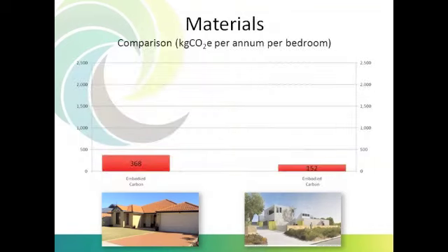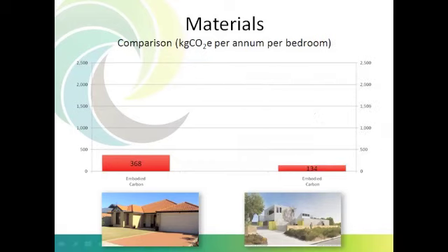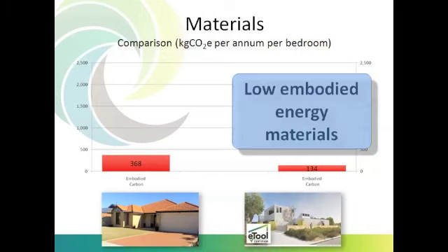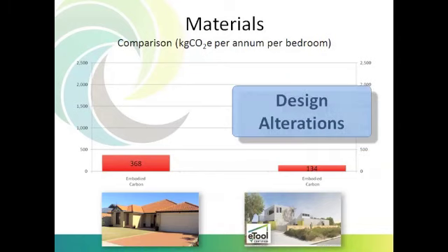Now let's look closely at the makeup of these buildings. Materials are selected for the design process. The new design with shared walls, high lifespan and light frame construction where possible is well under half of the benchmark. We can reduce this even further with the help of eTool by swapping some materials with low embodied energy alternatives, using recycled materials and making small design changes to eliminate components with high carbon intensities.